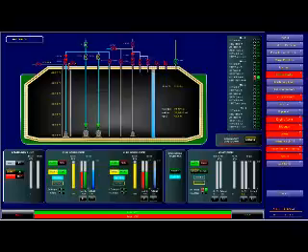Very simple, straightforward. LNG is one of the best liquids to handle, but if you know what you're handling, it has got multiple things which you will have to care about, which I'm stressing again and again. It's the thermal shock, the temperatures, the pressures. The tank which you have in front of you is not designed to sustain so much pressure, and if you are putting so much pressure, then you are stressing it. So the pressures are going down.